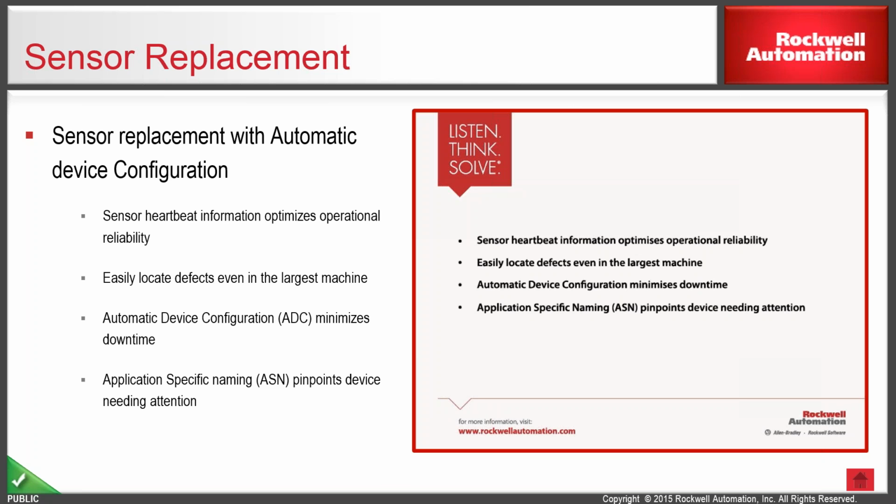So what you saw in this example was a very common recurring situation. One of the sensors is physically damaged, and the operator has to replace it. Now, by having all these sensors wired through IO-Link technology, the operator gets a message on his mobility device that a particular sensor is damaged. It points out and identifies which sensor it is.